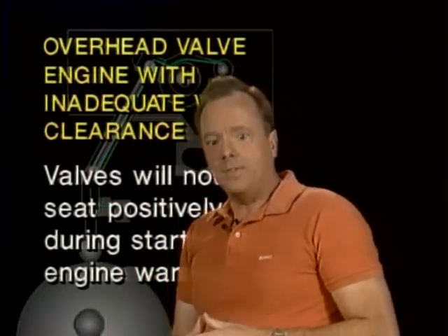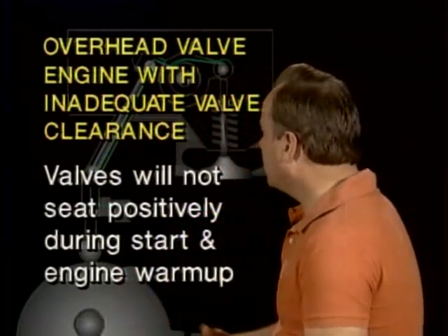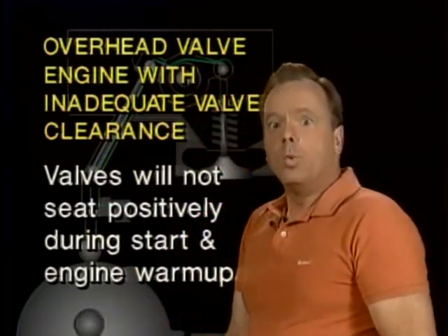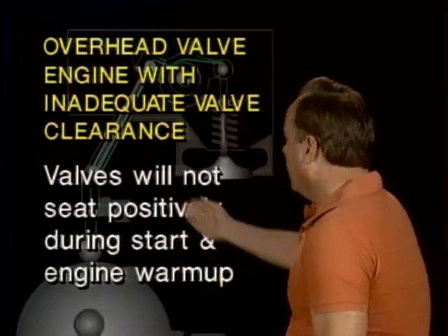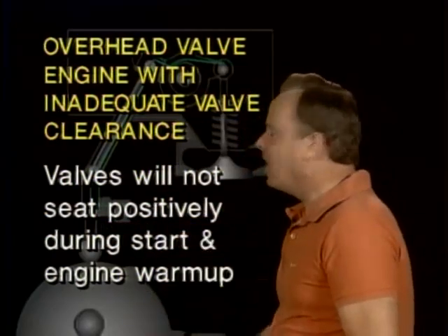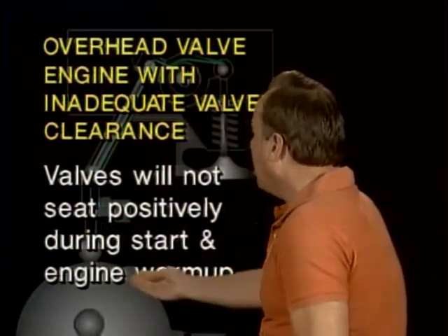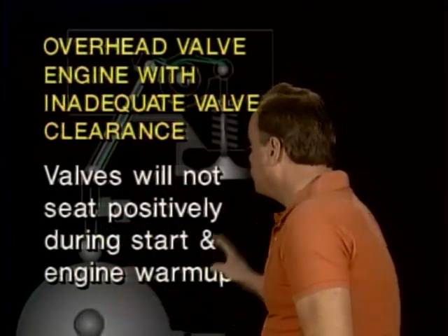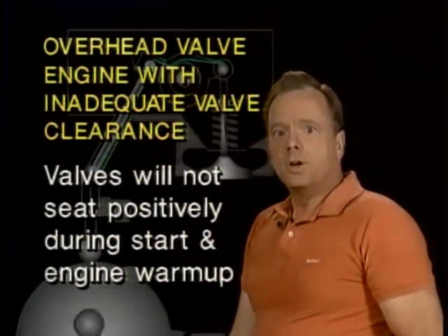Now, we've been talking about excessive valve clearance. What happens if you have inadequate valve clearance? And the answer is if you have inadequate valve clearance, you'll have exactly the opposite. The valves will tend to not seat positively because the valve tends to be open all the time, and during start and warm up particularly, the valves won't seat properly. So if you have inadequate valve clearance, you'd have a tendency to have the valves open too much, and particularly during start and engine warm up.